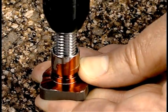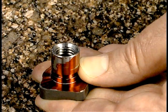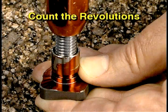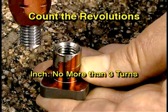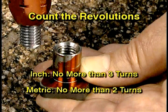If a go gauge threads properly, as with this plug gauge, remove the go gauge. Now screw the no-go gauge onto the part. When the gauge starts to bind, stop. Do not force the gauge. Then count the number of revolutions as you unscrew the no-go gauge. If the workpiece is measured in inches, and it takes more than 3 full turns to unscrew the no-go gauge, the pitch diameter is larger than the allowed tolerance. If the workpiece uses metric dimensions, you are allowed up to 2 full turns to unscrew the no-go gauge.